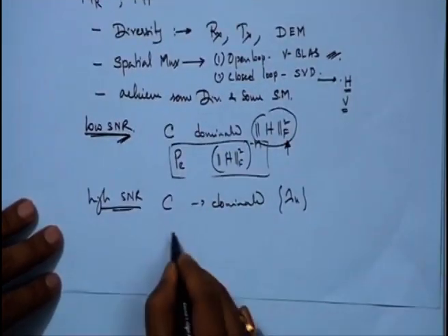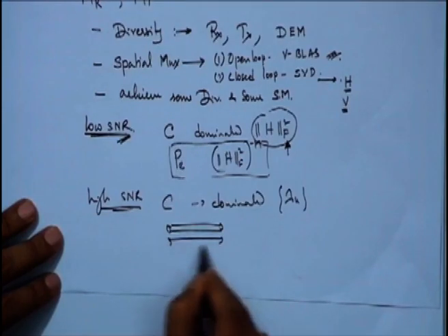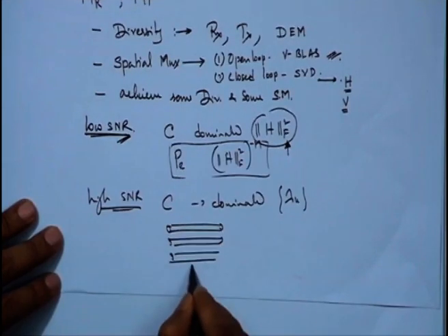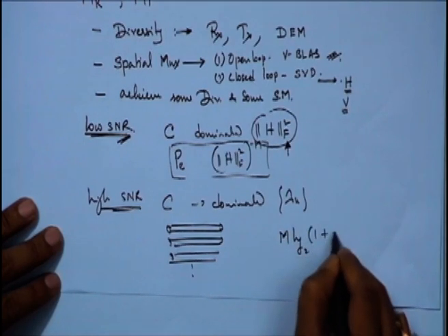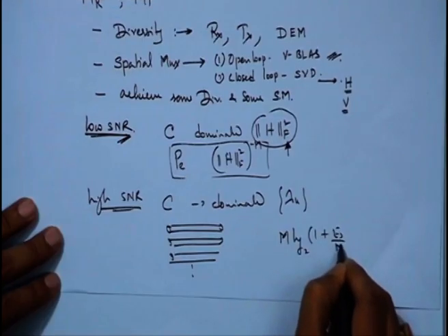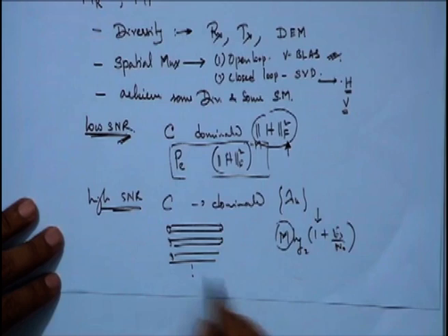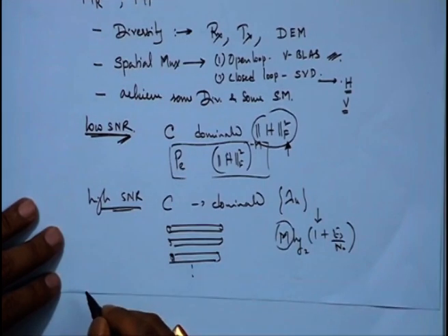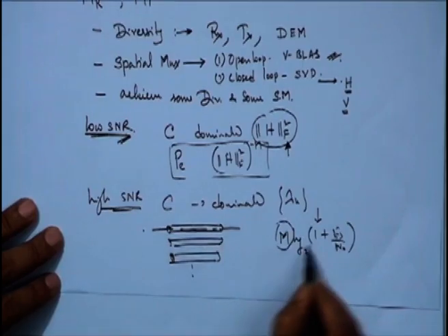So, when we divide the multiple antenna links into spatial parallel links, the capacity becomes log base 2 of 1 plus ES by n naught, that means m times the capacity of a SISO link. In the same tone, we should also say that these links have channel strength similar to that of a SISO link.